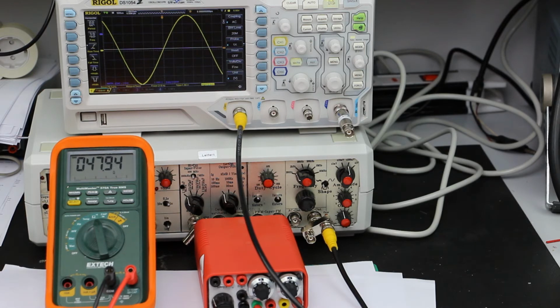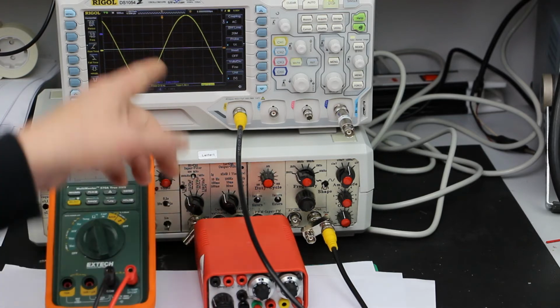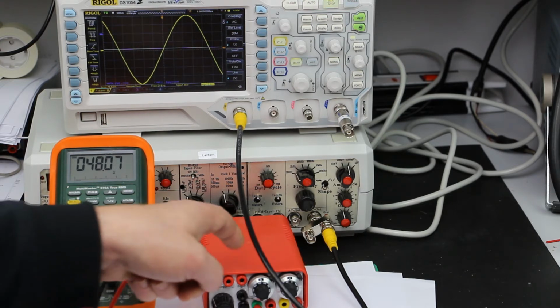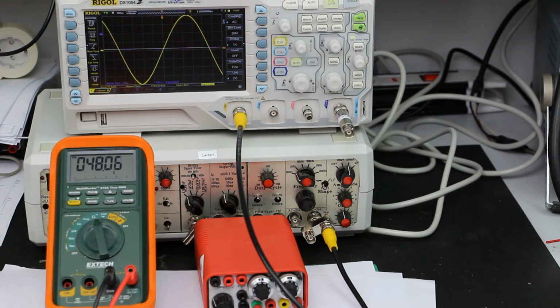If it's a low impedance source like a power supply or power amplifier, you should try this out only with power resistors. But as in this case, for 50 ohm sources, there was no problem in measuring with a simple variable resistor box just to find out the output impedance of the function generator. So that was test number 1, and let's go now to the second possibility.